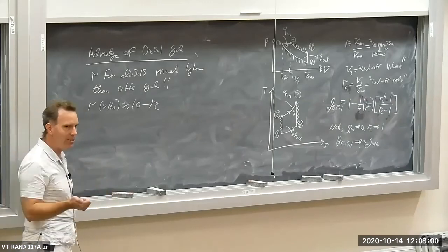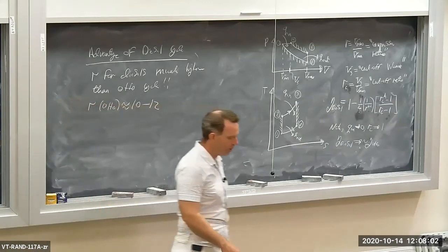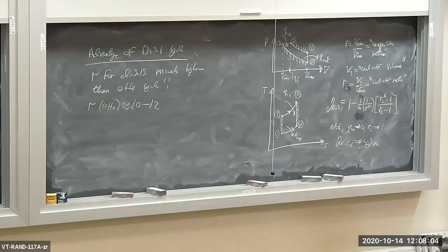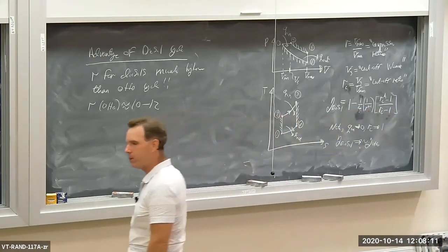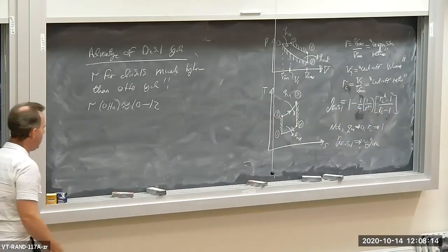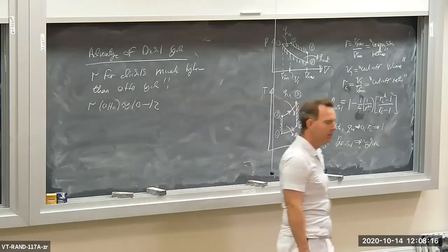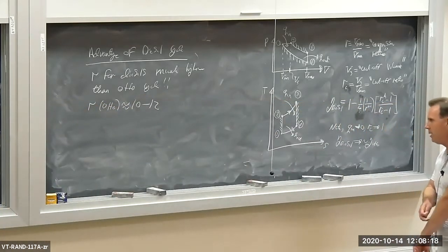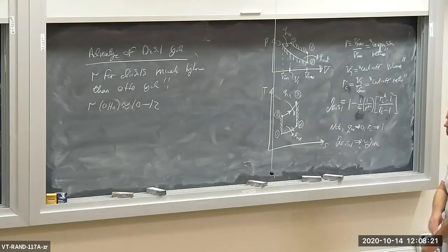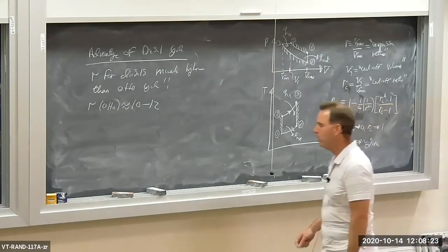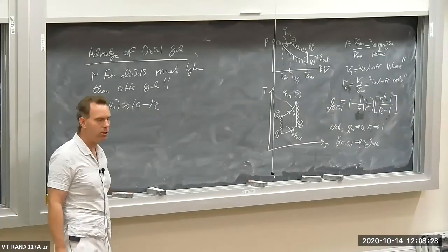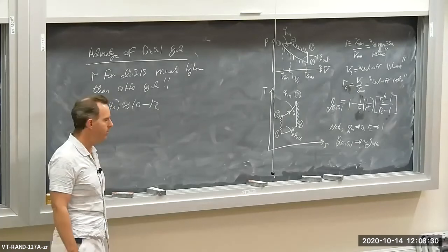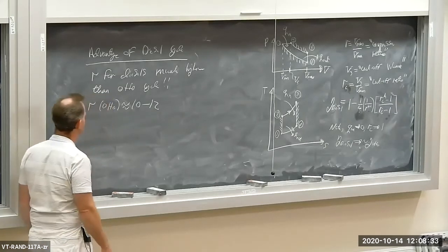And as I discussed last time, we can't really get a lot higher than that because if you pre-mix the air and the fuel together and you increase the compression ratio too high, you'll get uncontrolled combustion that causes knocking. Direct injection is helping with that a little bit, but anything higher than 10 to 12 and you start getting knocking, okay? You can use higher octane fuel, which is more resistant to knocking, but the highest compression ratios for Otto cycle are around 10 to 12.